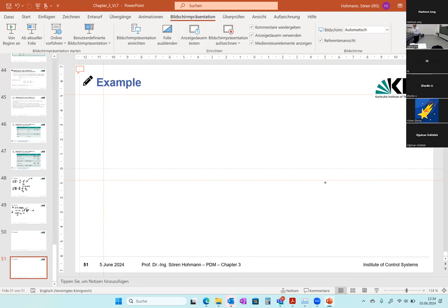So, for example, if you think of this bearing friction system, describing the friction is always a little bit difficult, so it might be helpful to combine the things. For the classical mechanical part, please use the model because it's straightforward. Describing the friction of such objects, being really precise, think of nanometer scale positioning, then friction plays an important role, and describing this kind of friction is really difficult. There are a couple of models to do that, but for the specific object there, data-based approaches might apply even better.